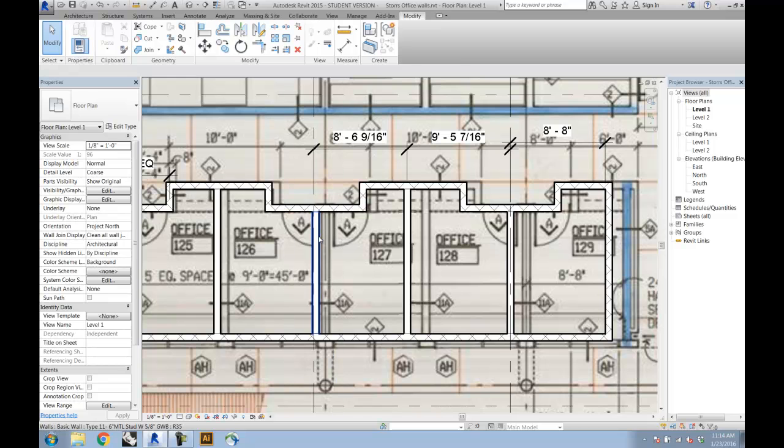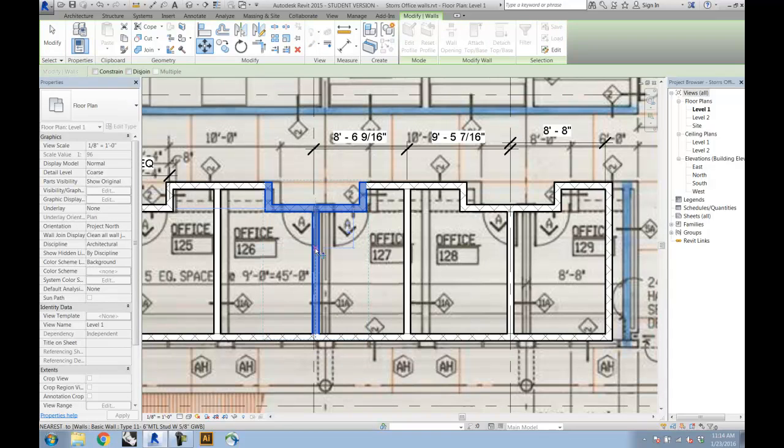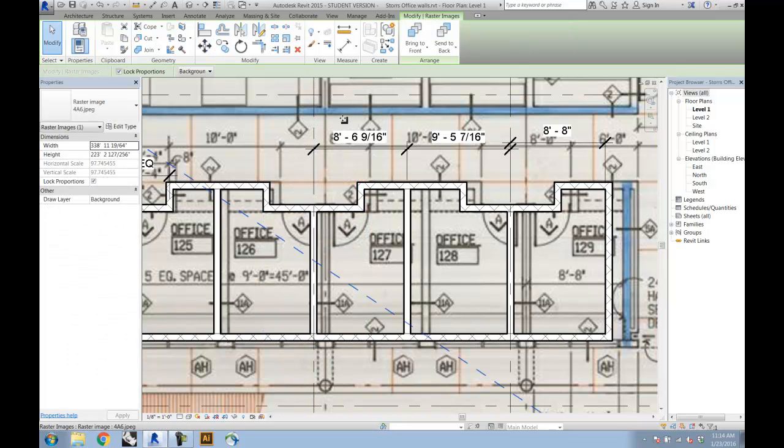This wall again is off out here. I want to adjust that first. So again, holding the control key, selecting this U profile, and just centering this onto the grid line. Now that that's adjusted, and I know that these two walls are correct, this is the one that's probably incorrect.